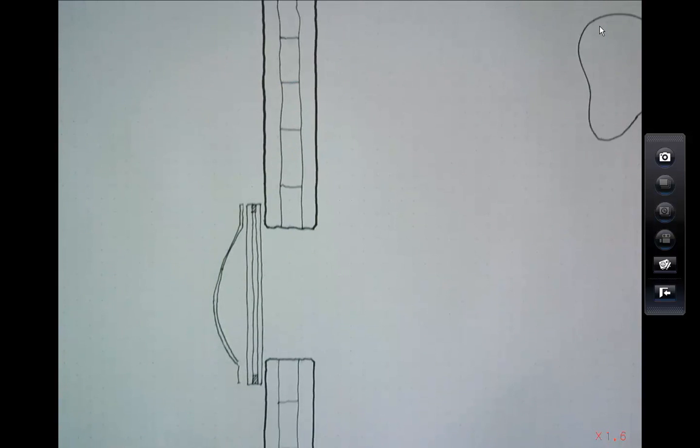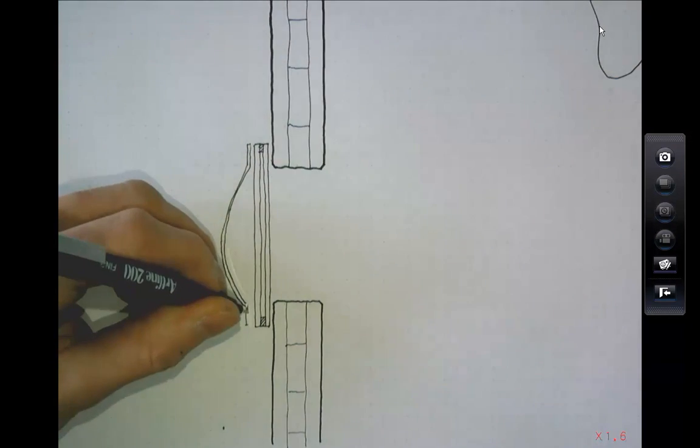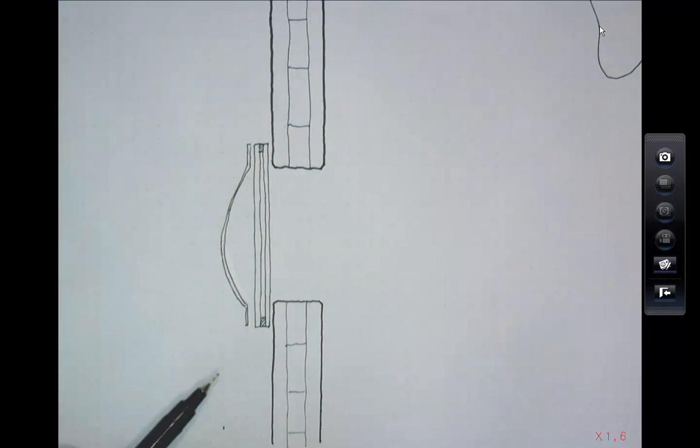So that's the double glazing. And you notice that this double glazed unit here is not sitting in a frame. So they've actually just bought a sealed unit of glass, which is kind of risky in itself because that means people are carrying that around site. If you drop it, you break it.